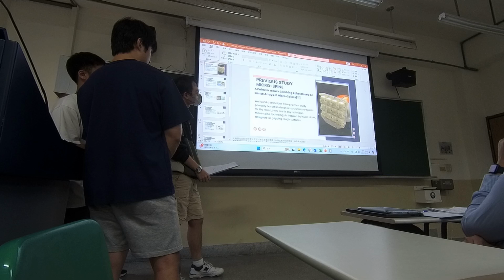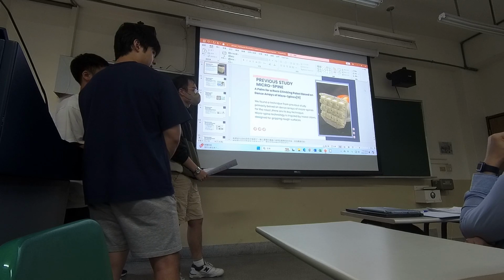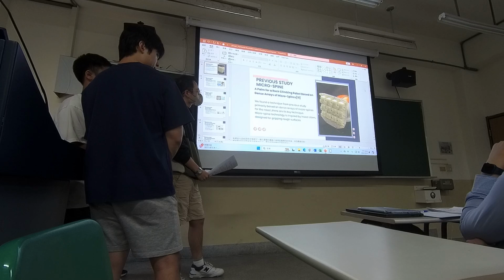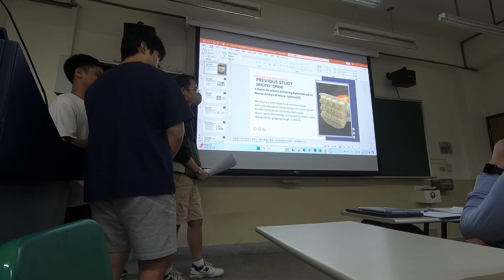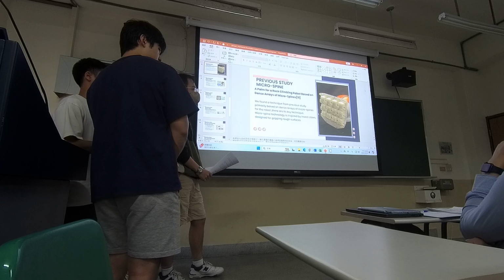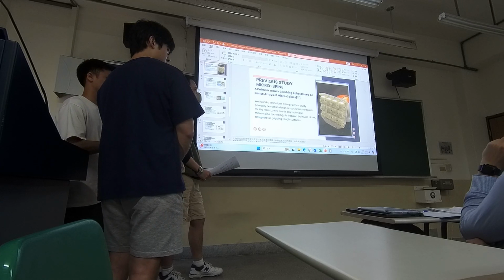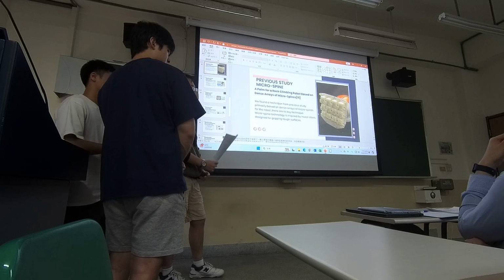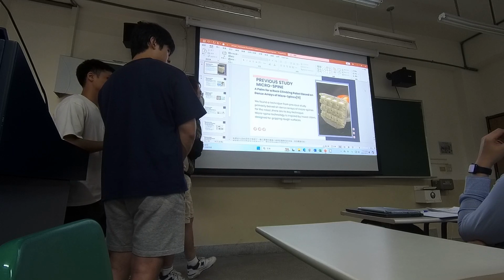So do you want to increase the friction or do you want to increase the clamping force? I think there are two different things. They are related, but they are two different concepts. You can have very strong clamping but poor friction, so it's slippery.